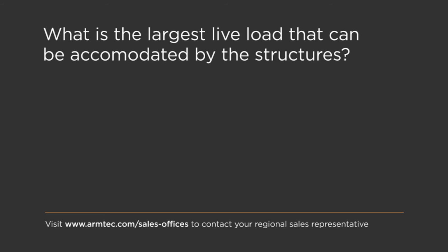Yeah, sure. So I'll tackle that one. We can handle fairly high live loads. Again, it's a function of the actual span of the structure, as well as the depth of cover. So we can handle the fairly heavy mine haul trucks. If we're talking about a single radius arch, obviously that's going to handle those heavy live loads better than a box culvert or something like that. So it's a case-by-case basis. Typically, we can increase the depth of cover to help distribute those live loads. But it's project-specific applications. If they're very heavy live loads, like railway loading or something like that, it's definitely something we can look at and potentially address.